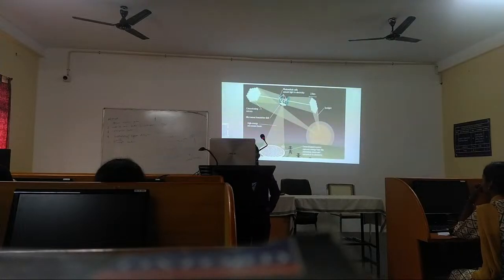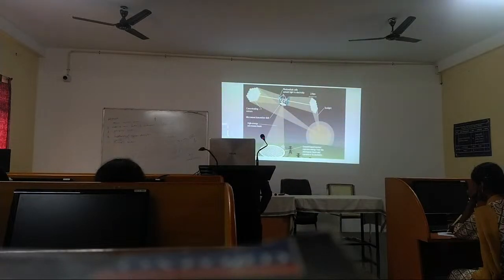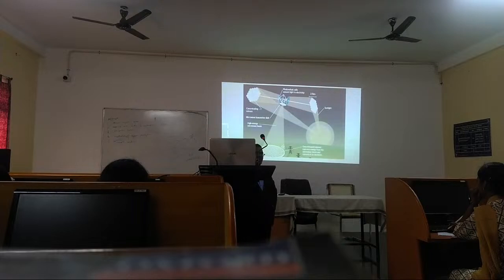Again, the microwave transmitter dish is the white circular element at the center bottom. From there, the power is converted from DC to microwave form using a magnetron or klystron, and transmitted to the rectenna placed on the ground. So a high-energy microwave beam is transmitted from space to Earth. The ground-based receiver, which we call the rectenna, captures the energy from the microwave beam and converts it to electricity, to be stored in batteries and supplied to the loads.